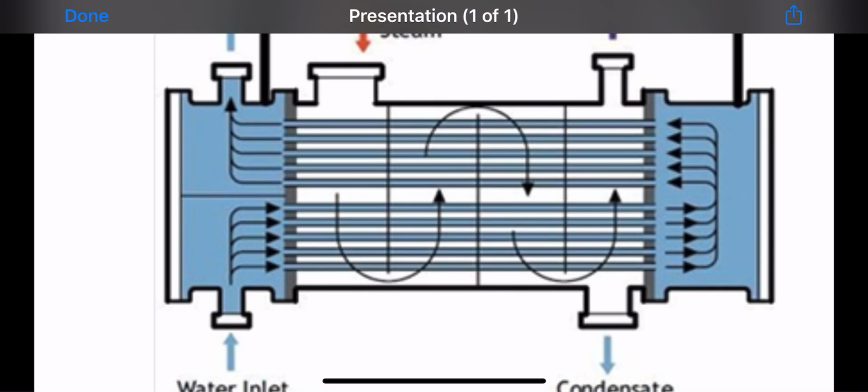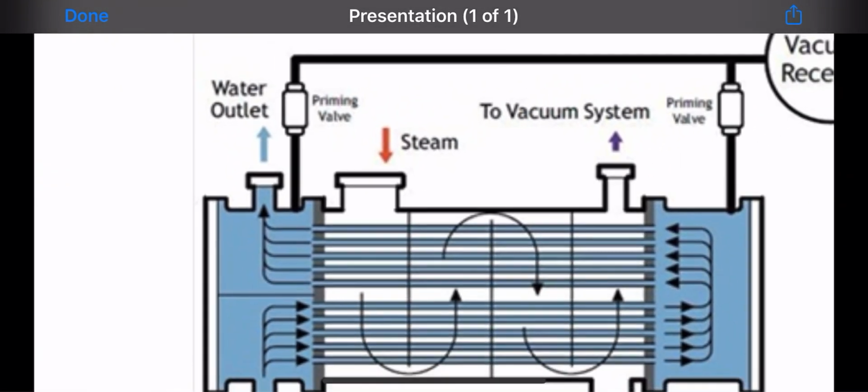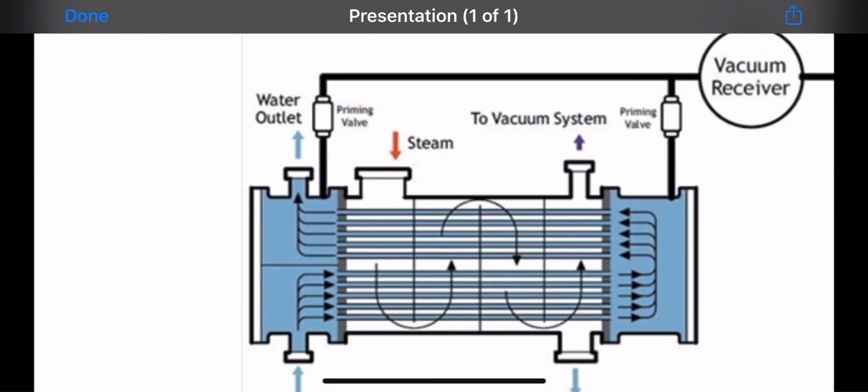And while this is taking part, we put steam or a different type or hot water inside that input, which goes through baffles. As you can see, these are half circles, which the hot water or steam goes through. Increasing the baffles increases the coefficient of the heat exchanger.